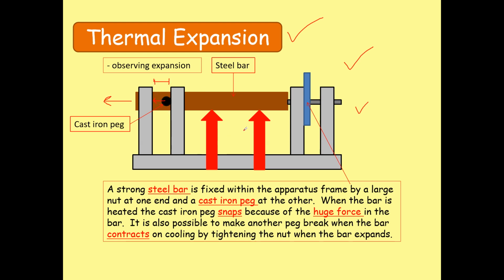If there's less temperature to be dealt with, then the gap is fine. But if we have very high temperatures to deal with, then we need to give more tolerance for expansion, so that this peg along with the rod can move quite a lot more, right, during expansion. So we need to give space to this peg, right?